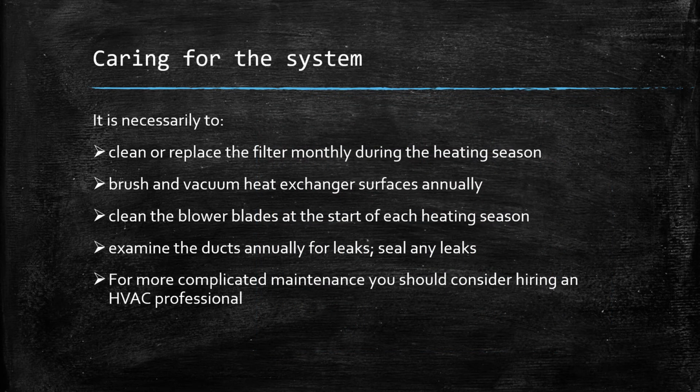It is necessary to clean or replace the filter monthly during the heating season, brush and vacuum the heat exchanger surface annually, and clean the blower blades at the start of each heating season. Examine the ducts annually for leaks and seal any leaks. For more complicated maintenance, you should consider hiring an HVAC professional.